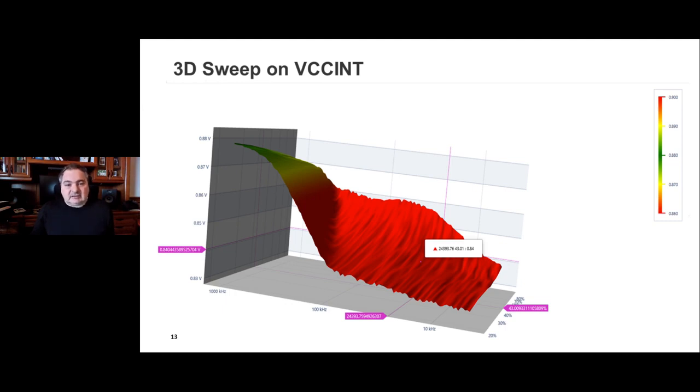test I like is the large signal output impedance. This is where we sweep a large signal sine wave current through the frequency domain and see how the impedance varies as a function of frequency, and we get to adjust the amplitude of the sine wave and the offset. That in itself is a whole new topic. But it's another fast way to identify fundamental weaknesses or areas that may need to be focused on in greater level of detail.